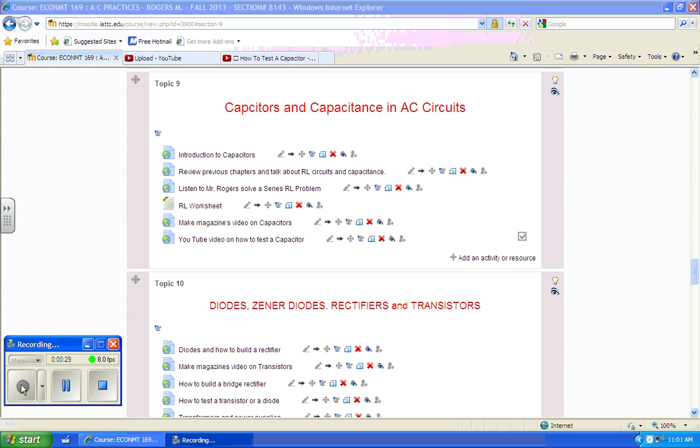It says VOM, but it means VOMM. What does VOMM stand for? Volt ohm milliamp meter. It doesn't read amps. It reads thousandths of an amp, right? It doesn't take big currents very well. To flow big currents through, say, a Simpson 260, which is a very good analog VOMM, you've got to do certain things like move the probes so that it does a shunt and things like that.